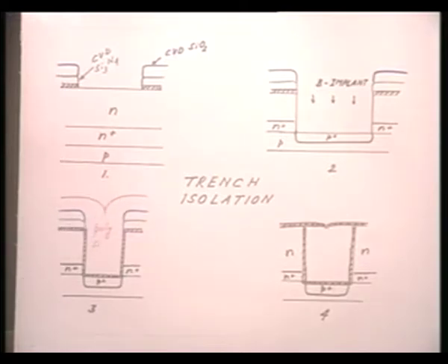This is another very crucial process because you want this polysilicon to be deposited uniformly in the trench. Unless you adjust the parameters of deposition carefully, it might not fill the entire trench, there might be gaps. Okay. So, you have cut your trench, the trench walls are lined with oxide and you have deposited polysilicon on top of that. So, you have filled up your trench.